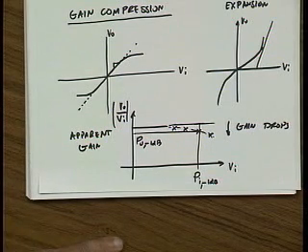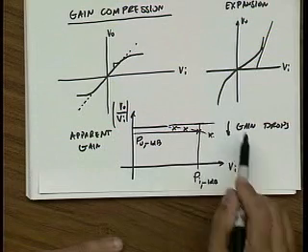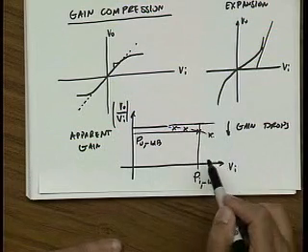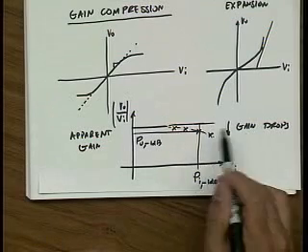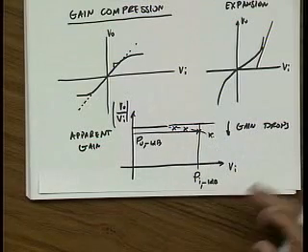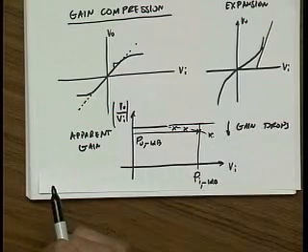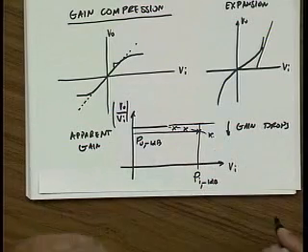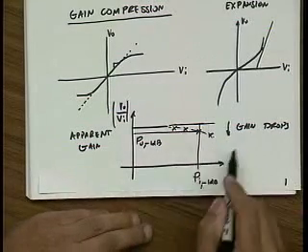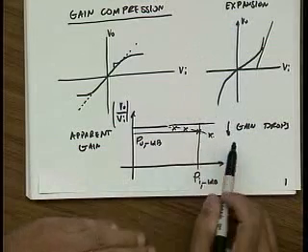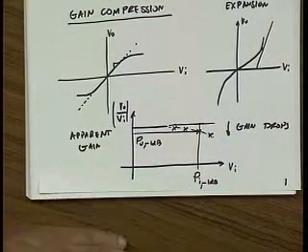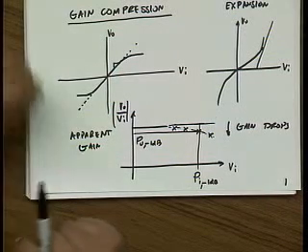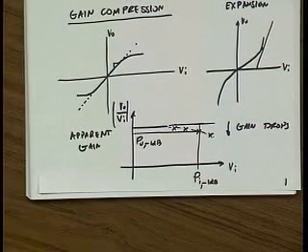compression point. Now the reason that we don't like to operate an amplifier beyond compression will become very clear in this lecture. So it might seem, sure, just use an amplifier out here, you're going to get less gain, but it's still a good amplifier, right? No, we'll see today why we don't want to use an amplifier in this region. So well below the 1 dB compression point, that's the small signal region where we like to operate an amplifier. Okay. Questions or comments?